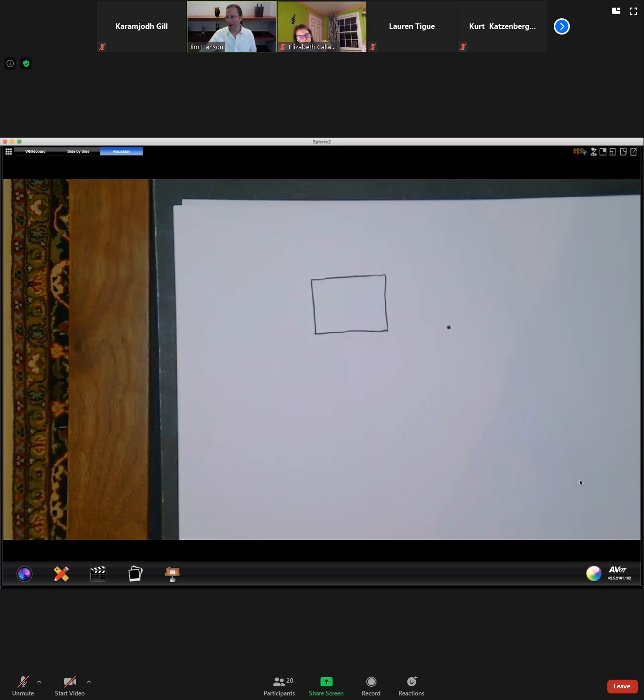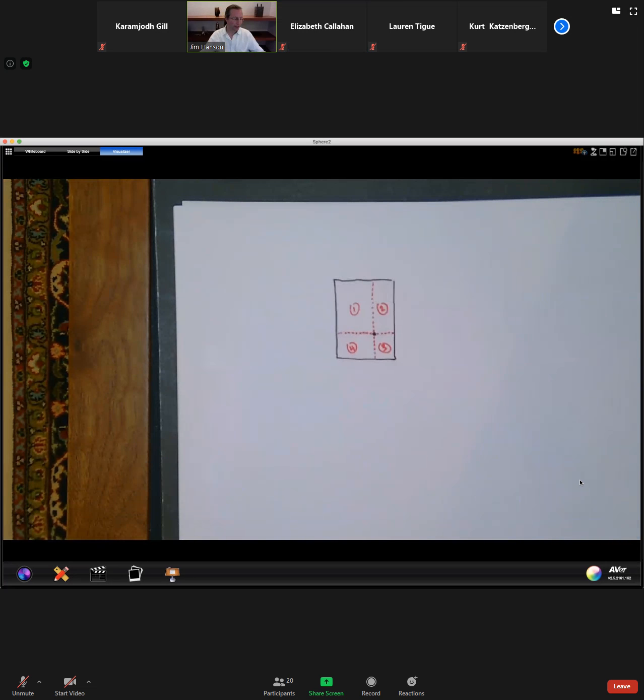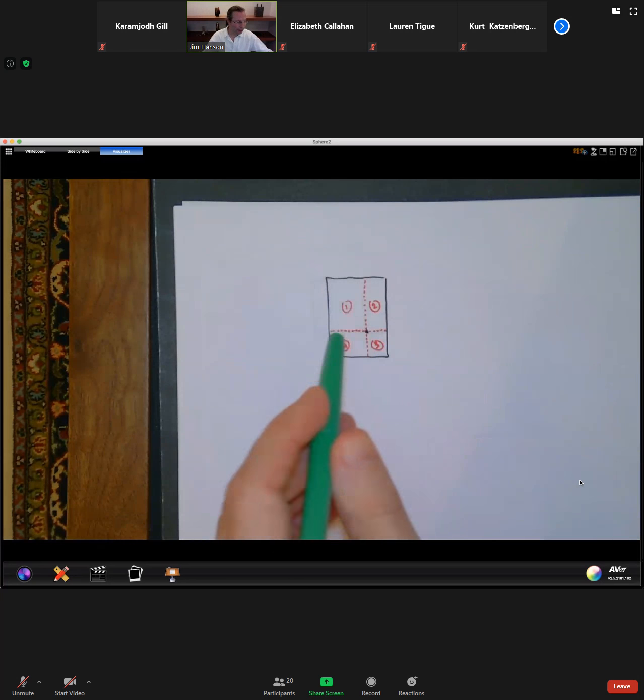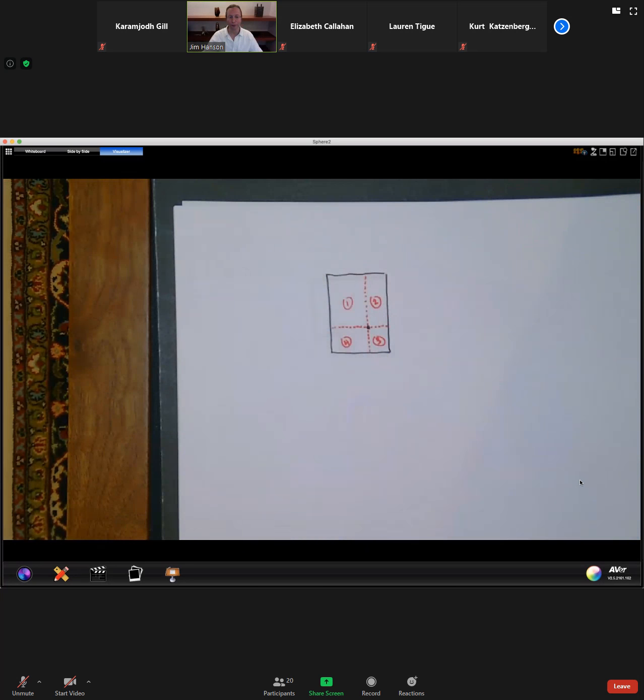You're on a path that shows some promise, but not quite there, Lauren. You're getting at something with like the method before. What did we do before? What was this process? What did that involve? We weren't utilizing the entire foundation. We were building what we could consider some virtual foundations just for the convenience of using the chart. Does that concept play out here? Do you think we could do that in this domain to force that point to be at the corner of a loaded area?